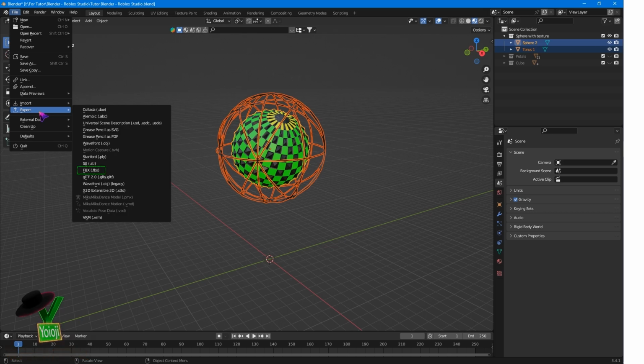FBX format. Of the good, the texture is loaded with the model, but it's worth clarifying that the texture should be in the form of a separate file in the appropriate format, usually PNG. I'll tell you more about textures in another video, a link to which will appear in the description as soon as it is ready. You may also need to place the texture file in the same folder as the 3D model file in the FBX format. This is in case the texture is not loaded during import along with the model.